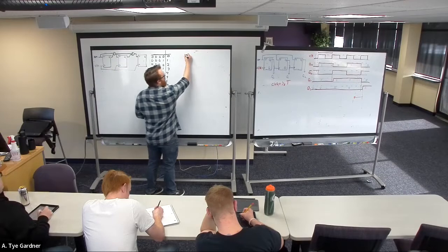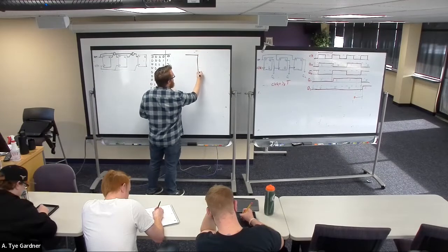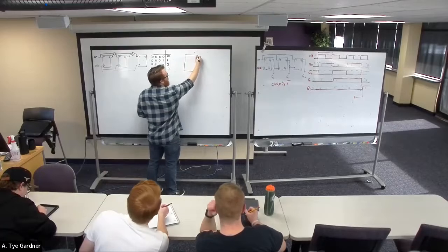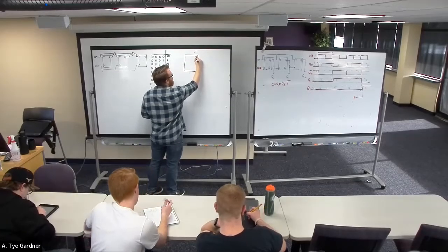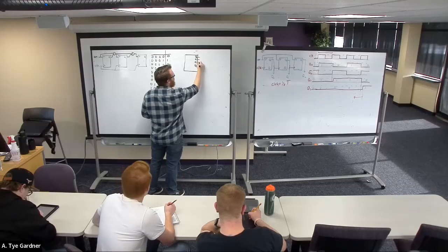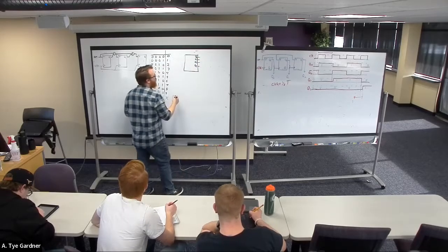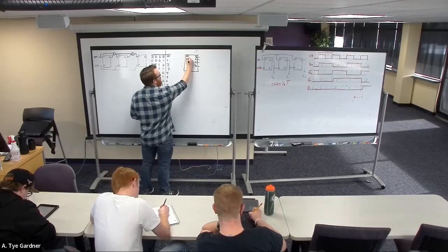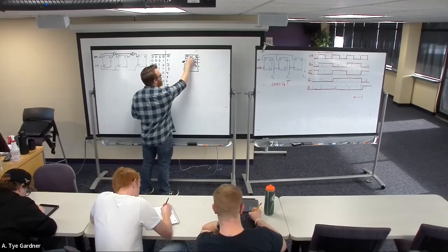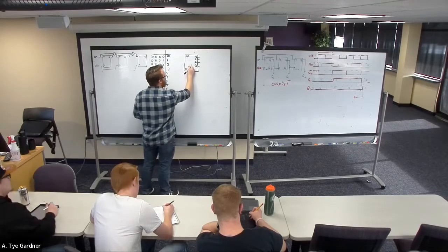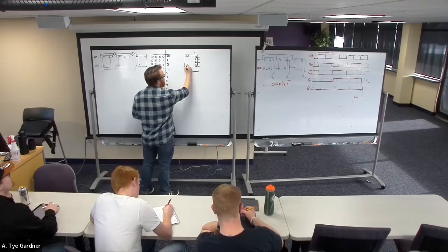And so we end up with a counter. We would go build this logic, and I'm going to have Q0, Q1, Q2, Q3, a 4-bit output. I want an enable, a signal called load, and I need a clock.